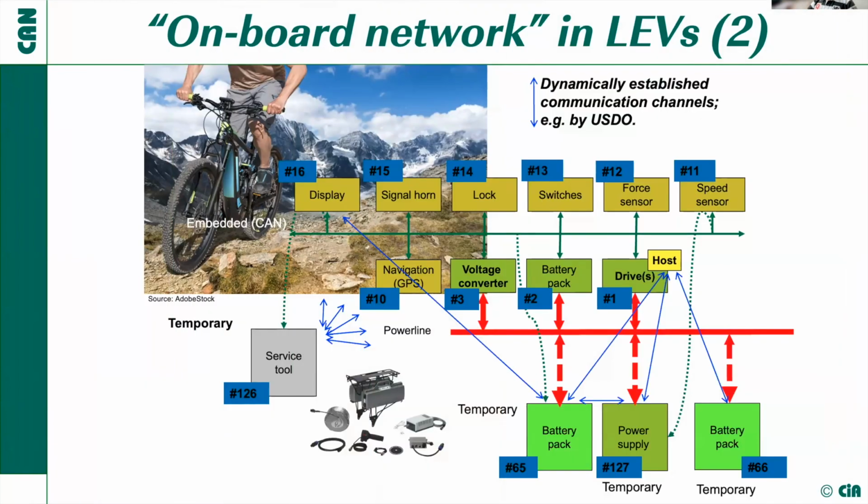And now when it comes to dynamic node and network ID assignment, then to run a CANopen FD system in a proper way, all of these devices need to have a unique node ID. So the host controller can use the CANopen services such as the USDO and can now access all the devices.